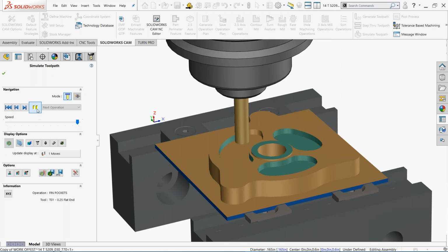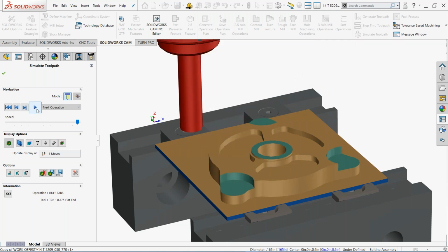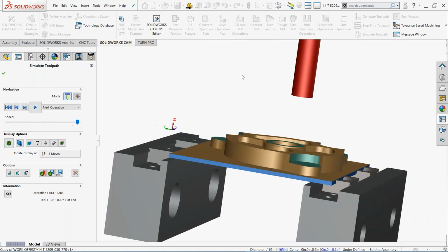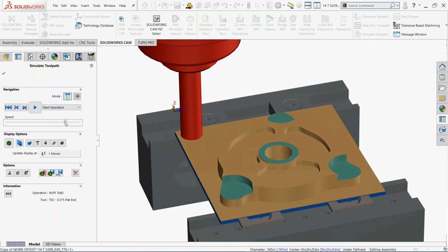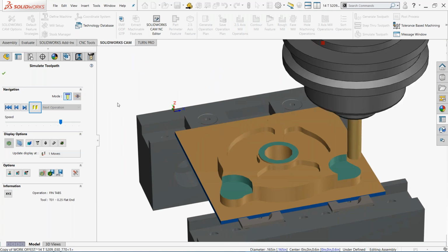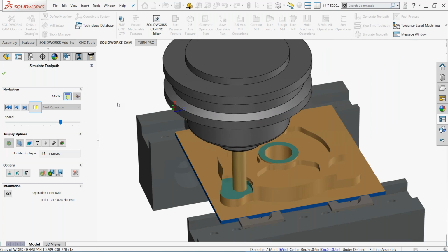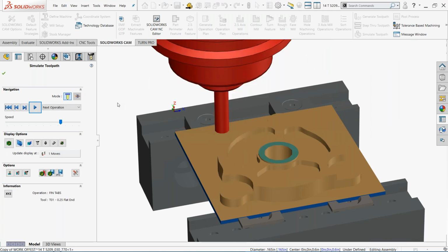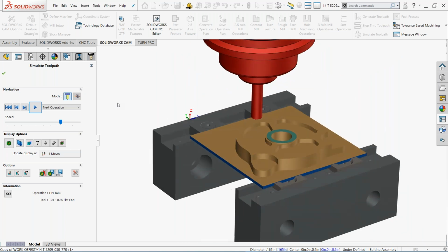Let's come in and just finish up each one of these profiles. That looks great. And now let's take a look at the tabs themselves and see how that roughing is doing. And you can see we've roughed those out with high-speed machining technique as well. Let's just come in and finish profile each one of these. And again, you'll be able to see over here that fine adjustment that we made so that we're getting a nice dispersion of our cut. And so far, so good.